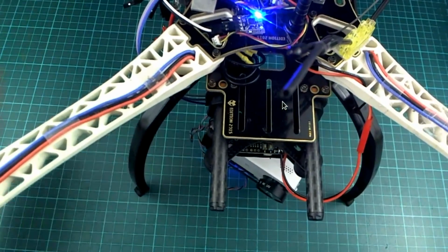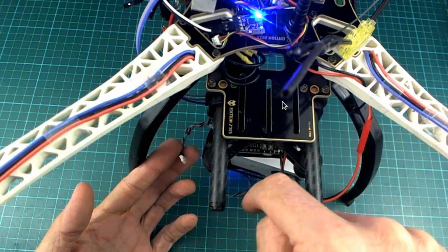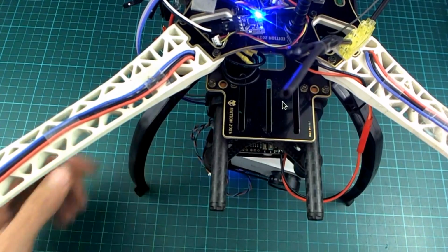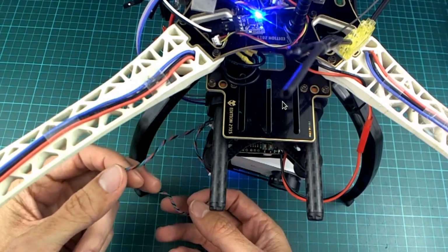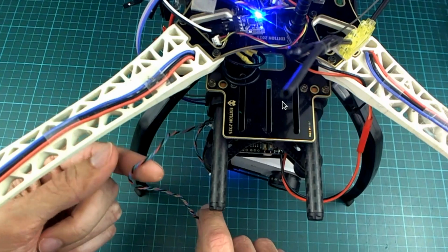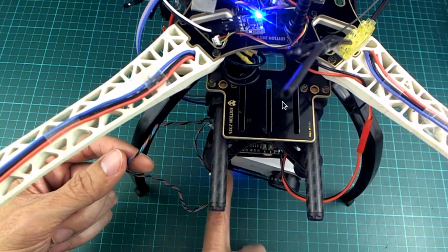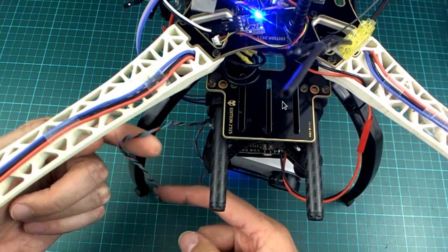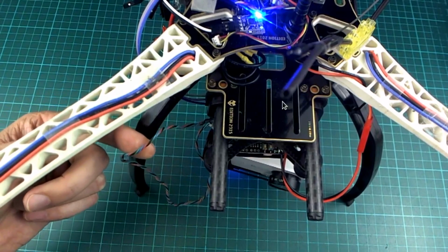With a bit of investigation, I found that it was to do with this wire going through the yaw motor. It was having trouble. The signal just wasn't clean enough to read properly. So what I've done here is I took one of these same kind of wires off one of the other gimbals that I had that got a bit broken, and I connected this wire up directly from the gimbal controller board to the IMU on the bottom of the gimbal plate, right underneath the camera, and it's not going through any of the motors at all. So it's completely free and outside of all of the structure of the gimbal, and that works fine.